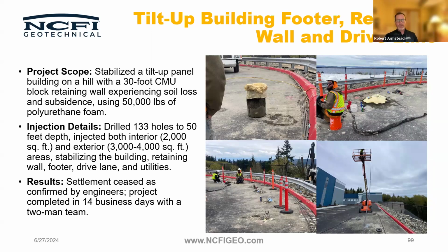And I've been hearing from some of the top polyurethane guys out there that they're vastly starting to extend the length of their injections, and they're doing that through a variety of techniques. Some of it is through temperature regulation within the poly to offset reaction time. They're using different materials such as PEX to help increase the travel, and using some of our systems that have a slower reactivity time in order to get it down there. So really that needle has been constantly moving, especially over the last 5 years.